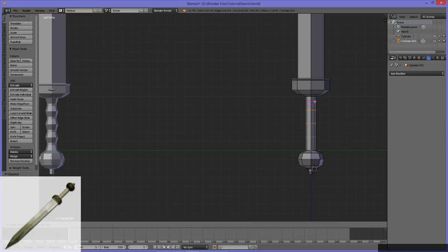If I move the mouse wheel, this doesn't show up in my key show program, but if I move the mouse wheel, you can see I can bump that up to 2 pieces, two edge loops. There we go. Again, I'm going to click that, and then I'm going to press escape to confirm it so it's right in the center. We're going to do that for all of them. This one. Oh, you have to use the scroll wheel while the lines are still pink. So I'll click and then press escape so those are in the center.